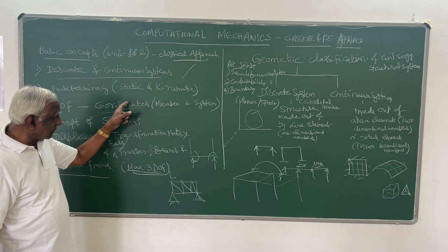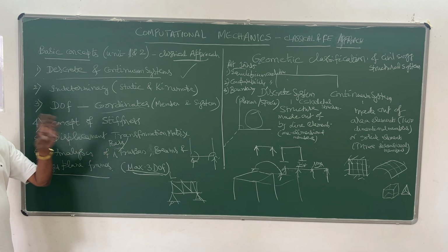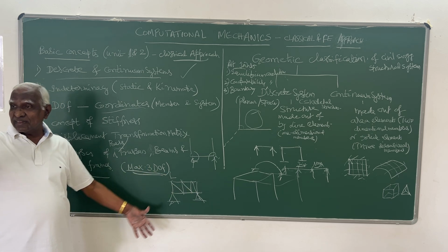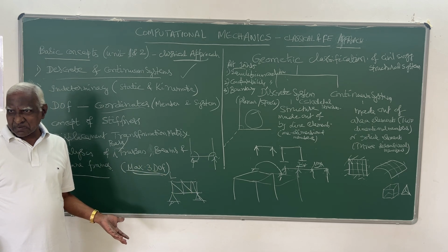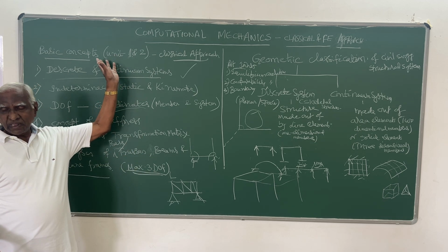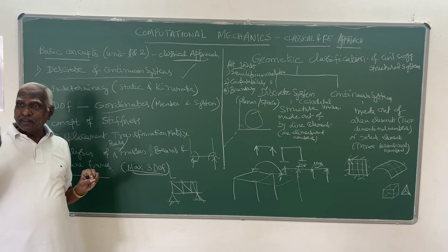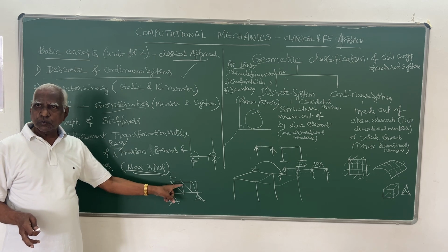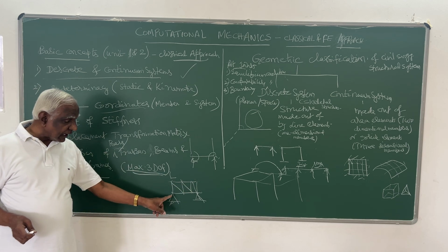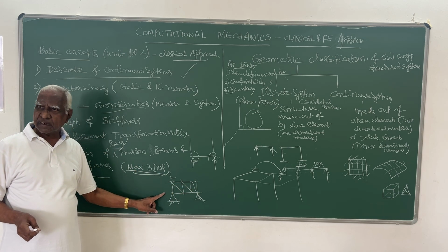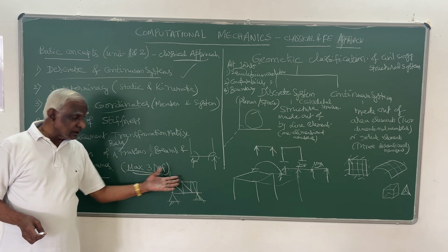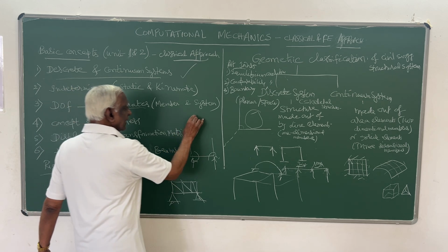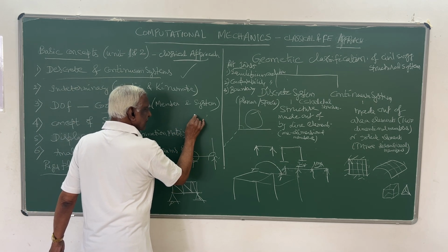Right? But in your syllabus, that's why this particular word is a maximum 3 degrees of freedom. So this particular type of truss, wherein you have more than 3 unknown displacements, because it is a direct stiffness method, only we take unknowns as only displacements, not forces. Only if you take displacements, two displacements per joint, other than boundaries. Boundaries here no displacement can occur, here also no displacement, other than at 12, so this problem cannot be solved. Only maximum 3 degrees of freedom is only a truss like this.